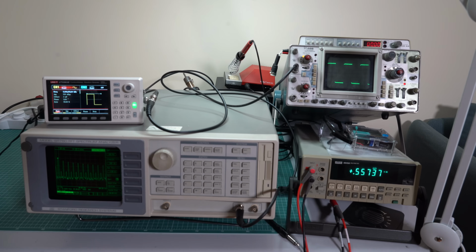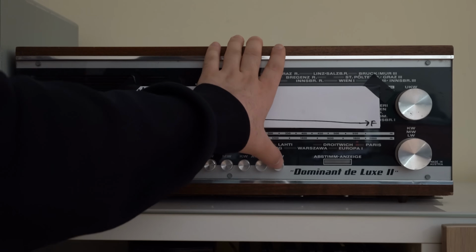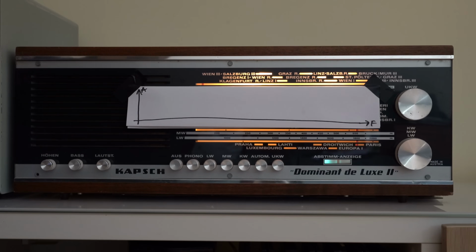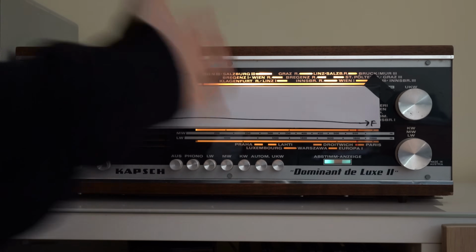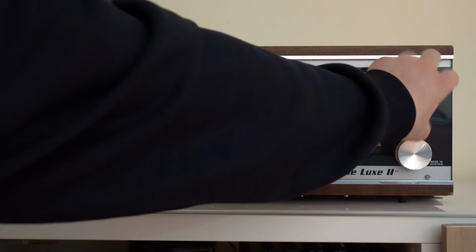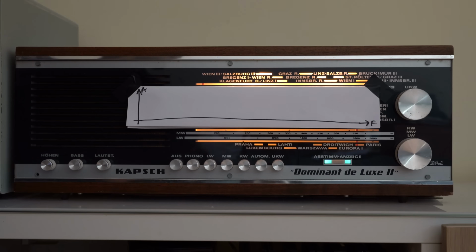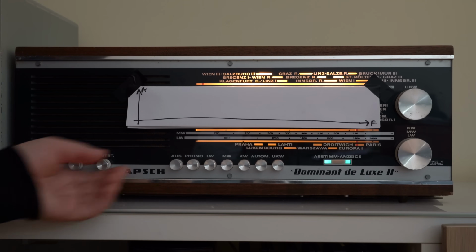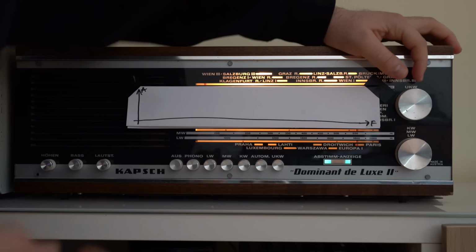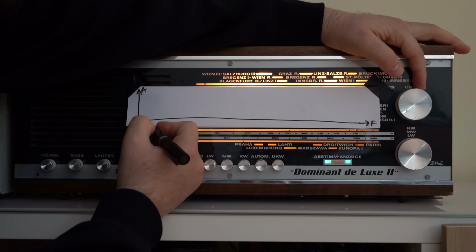And I know, it sounds like you need a really exotic piece of test equipment to do this, right? Well, not really. That's actually what the radio does. If you think about it, the radio already has a narrowband filter that's tunable using this frequency knob, right? So that means that we can play with the radio and get our own frequency domain graph of the FM broadcast band. So let's give it a try. Let's sweep it across the band and see what we get and trace our own graph.